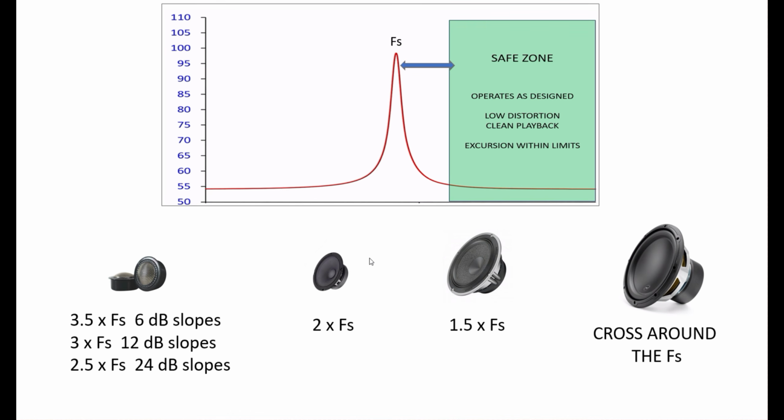And this is the problem with playing your speakers low. 160 is still a long way from 105, but as you go down in frequency, the multiplier in terms of the excursion that you need from the speaker to play that frequency at an equivalent SPL level ramps up exponentially. So you've got to be careful about crossing your speakers low when it comes to mid-range.